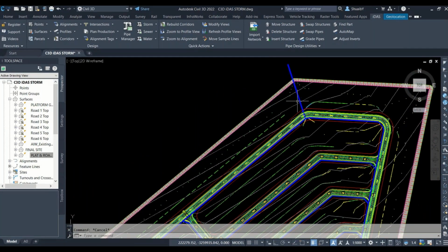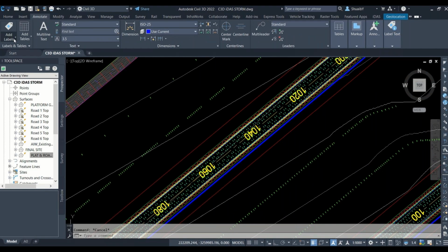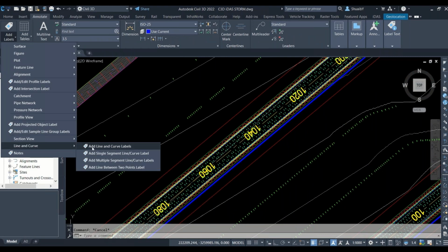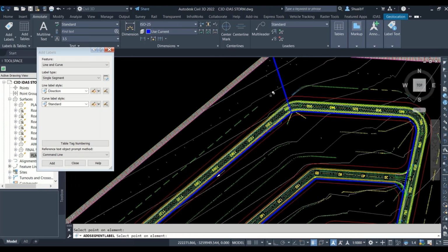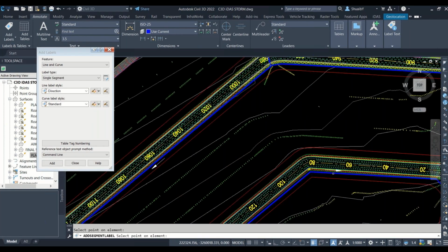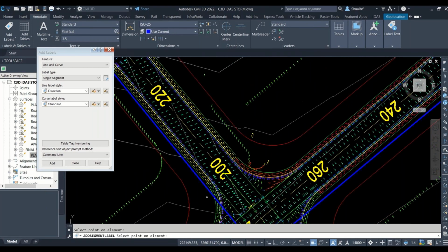Of course, that's the position of the outfall on the top there, and of course the red lines denoting the area that I could work in. Now, sometimes when someone draws a polyline, it might not be in the correct direction because they're just giving you a layout. Again, with the label sets or styles built into Analyse, it's quite simple to navigate this and see what the directions are. As you can see already, the pipe on the left-hand side is going in the wrong direction because I want it to go towards the outfall. Same with this line here, right?